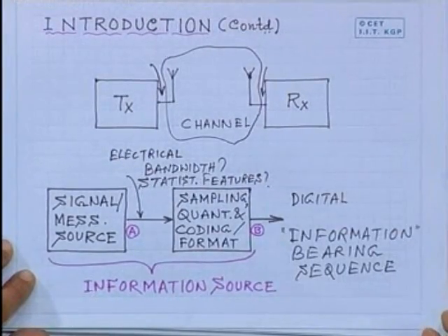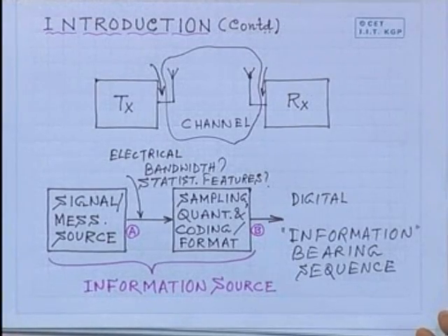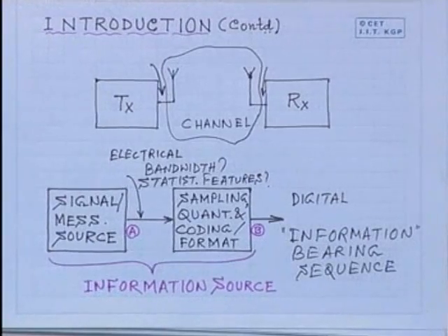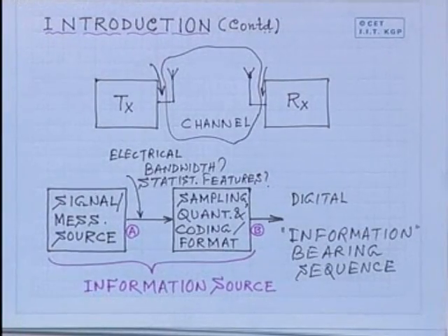You can try to transmit digital signals, but for communication systems you are very pressured in terms of transmission bandwidth, the amount of bandwidth that you are utilizing. The problem is not the same if you are designing a radar system, where pulse transmission is a very popular scheme. You can transmit pulses, but for communication systems usually it is a CW transmission scheme, continuous wave transmission. That is how you require minimum possible bandwidth, and utilizing minimum possible bandwidth is a very important issue in the design of the system.